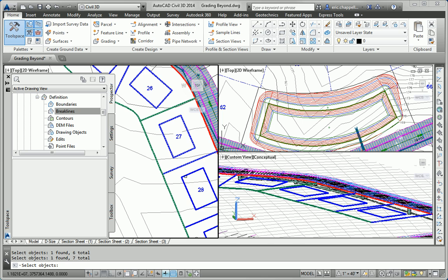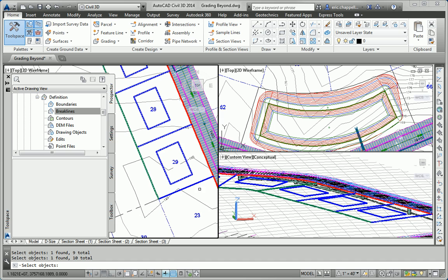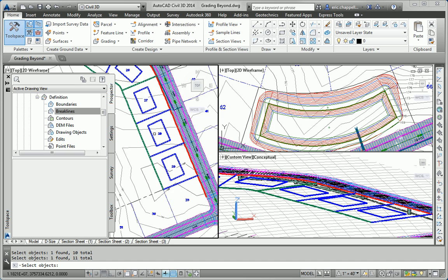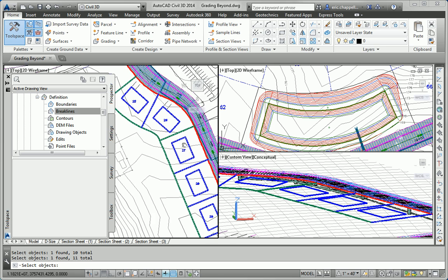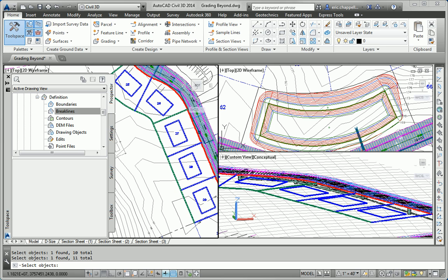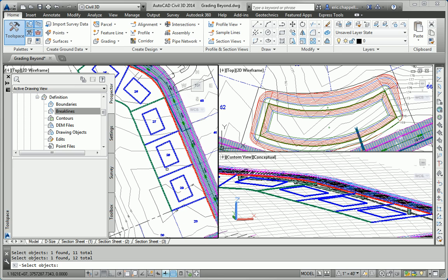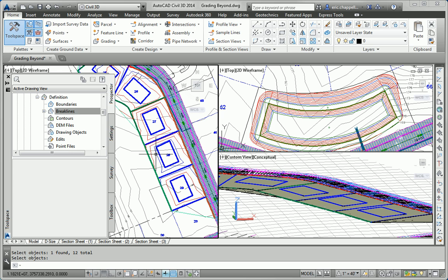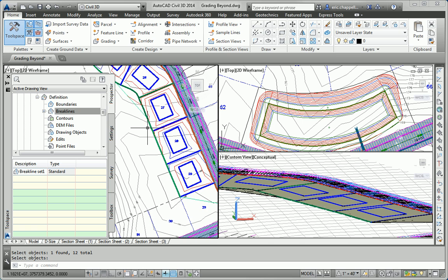While I'm picking these lines, I'm also thinking I'm going to need to supplement these lines a little bit, especially these lot lines from front to back, there's not a whole lot of data points on them. There's only two, in fact, one here and one here. The building pads only have, I think maybe 6 or 8 data points, so there's not a whole lot of points there to define a surface with. And I want to make sure I pick the road feature line as well. So those are all my feature lines. And that actually looks pretty good. I didn't do any supplementing or weeding.